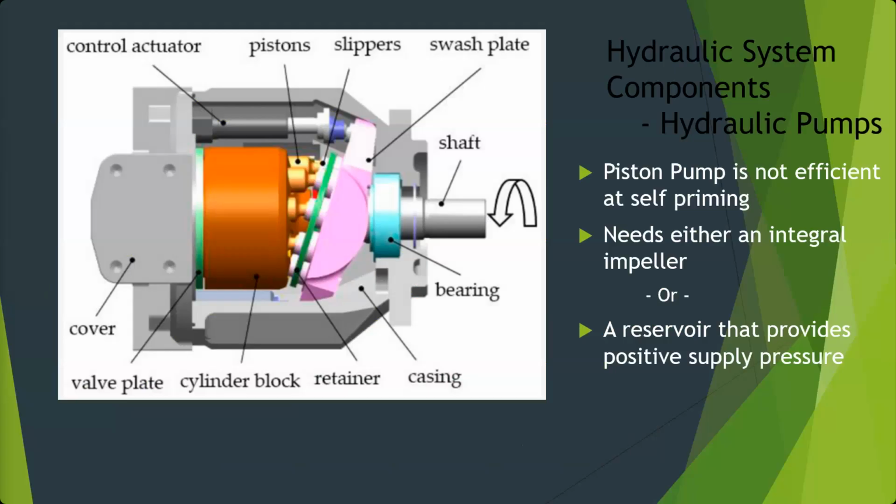Once the pump is up and running, it's going to be able to pull that. But if the pump's filled with air, it'll cavitate, and all it'll do is basically push air back and forth and not do a great job of getting fluid going. It will eventually, but in that time that it's cavitating, it can actually cause damage to the pump. So most of these pumps are going to have some method to help kick off the flow of fluid.